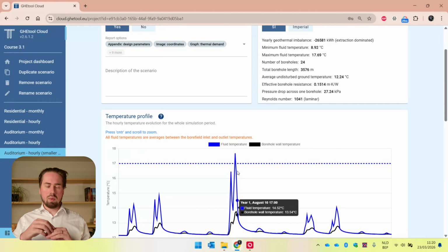Let's say, because we cross our limit, but it's only during 1 hour and we have a very high resolution because it's hourly. But this does not mean that this hourly profile is actually the truth. It really depends on what weather profile or what occupancy profile you use for your dynamic simulation. So to end this summary, because you can see we just avoided a significant oversizing, it's really important that you understand your hourly profiles. What's behind them?